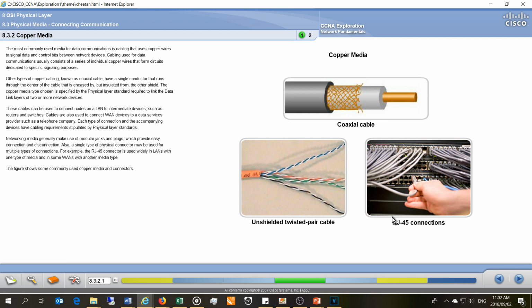Now here is just an example of some of the copper media. You all know the unshielded and the shielded twisted pair. The shielded just means it has an aluminium wrapper, and there often is an aluminium wire that runs with this, and it goes to the RJ45, and it must be touching the shielded RJ45. Those are mostly used in hospitals and installations like that, where there are various medical standards requiring shielded cable.